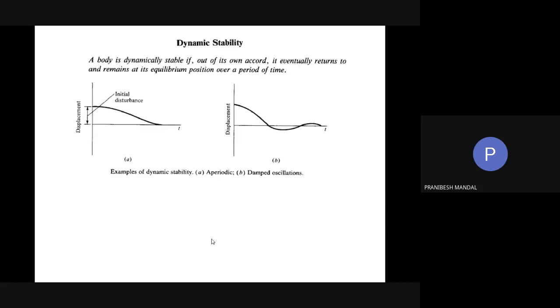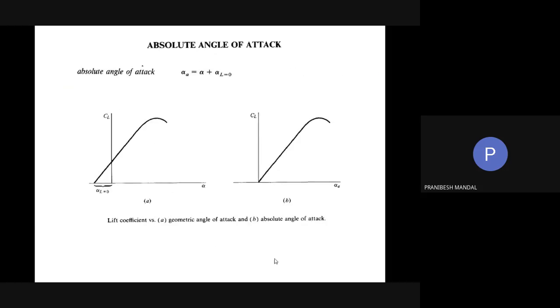What is the CL versus alpha curve? This is the CL versus alpha curve, isn't it? Yes, sir. So for our case of small alpha, it is well within the straight line limit, that is, well within the stalling limit, isn't it? Yes, sir. So we can say that if the slope of this curve is A, then CL equals A into alpha. Yes or no?